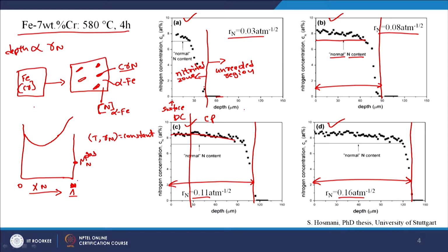Now, for chemical equilibrium between two phases, in this case gas and solid, we impose that the chemical potential of nitrogen should be the same, that can be read by placing a tangent to this Gibbs energy curve, with this as an intercept, as this one is constant, and wherever it makes the tangency with the Gibbs energy curve, that is the so-called equilibrium.